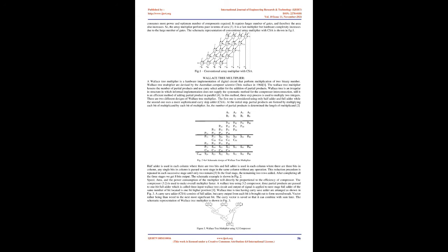Some of the known parallel multipliers are array multiplier, Wallace tree multiplier, Booth multiplier, and modified Booth multiplier. These multipliers are discussed in the following text, keeping focus on Booth multipliers. The Booth multiplication algorithm treats both signed and unsigned numbers. The main use of the Booth algorithm is to reduce the number of partial products by reducing the number of multiplier bits. It is used in different recoding schemes such as radix 2, radix 4, and radix 8. In the Wallace tree algorithm, the number of sequential adding stages is reduced, which is used for improving speed.